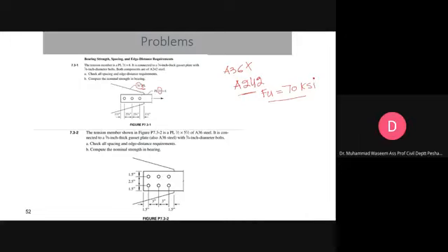So now you become more wise. So what you are going to do, for this gusset plate only, you will perform this check for this plate, not for this. Okay, because the material is same. This is A242. This is A242. If these were two different materials, then there was a problem. Then you have to evaluate both.